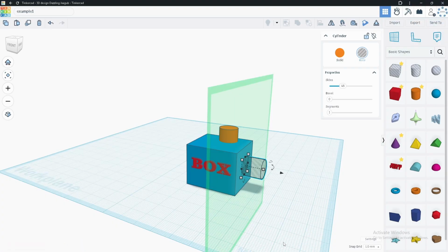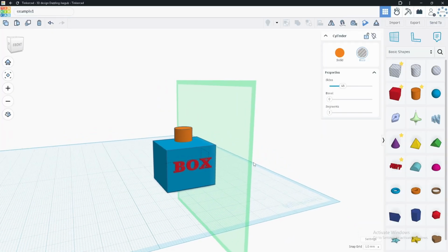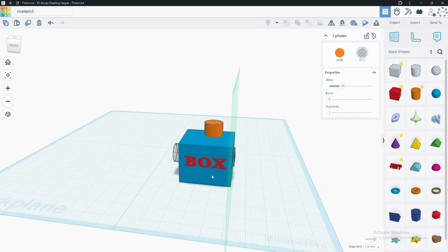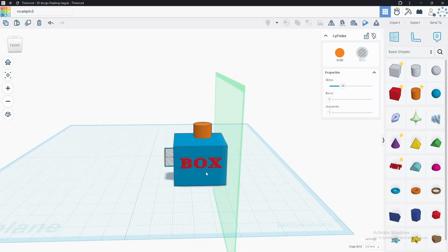All right, let's extend it and then use the cone to move it into our shape. Now let's use the right click and make sure we're all the way through. Uh-oh, we're not quite through yet. So we're going to have to extend it and push it back through. Now we're all the way through. So it's really important that you orbit around and you're checking what you're doing.